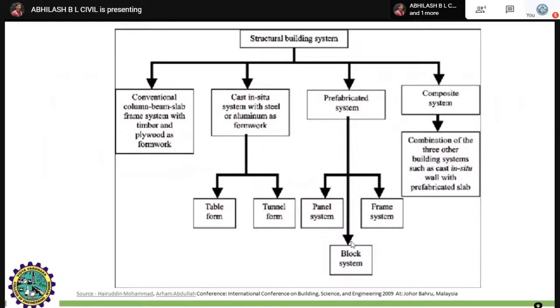Later on, plinth. Next, masonry, sill level, windows, doors, that is the opening part, lintel level, sunshades or chajjas, lintels and chajjas, again masonry. Later on, roof, finishing of the roof with surki material or any other permeability material. Coming to the next, parapet wall. Next is the finishing, painting, like this. These are the phases. You cannot come from the top down in this construction, right?